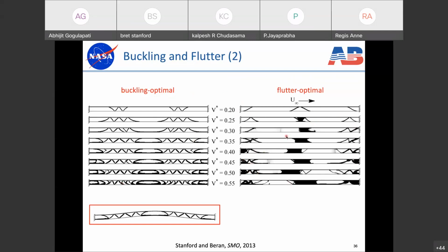But you can see here for the first time, I'm showing topologies where the SIMP method is starting to struggle. We have some blobs of gray here, for example. Here again, here's a third instance where we see it. So this is a situation where the SIMP method is providing to us a topology which has lumps, which has big blobs of gray throughout, which we really don't want to see. And the reason this is happening is because of this mode switching issue that I mentioned previously.